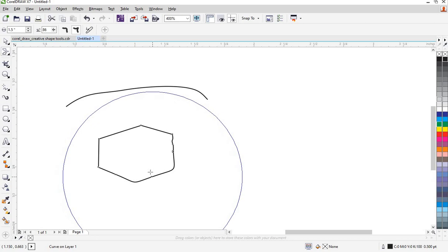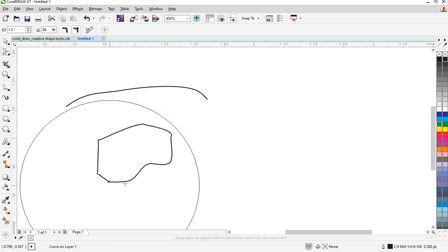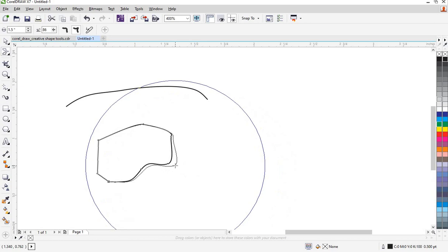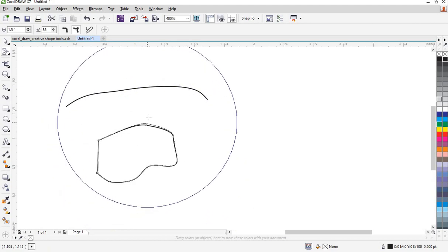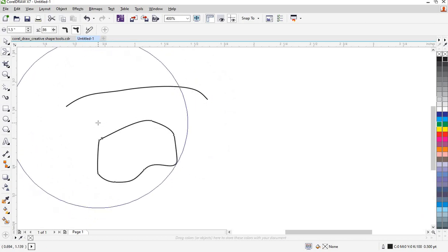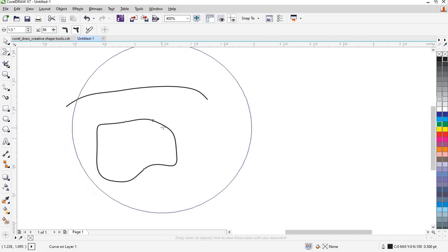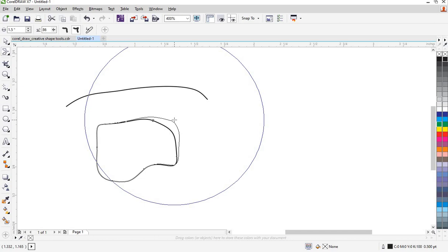I can drag this inside. I can drag by choosing a point on the outline of this polygon outward. Similarly, I can change the shape of this polygon in whatever shape I require by using smear tool. For this, any point on the particular object has to be chosen and dragged inward or outward.